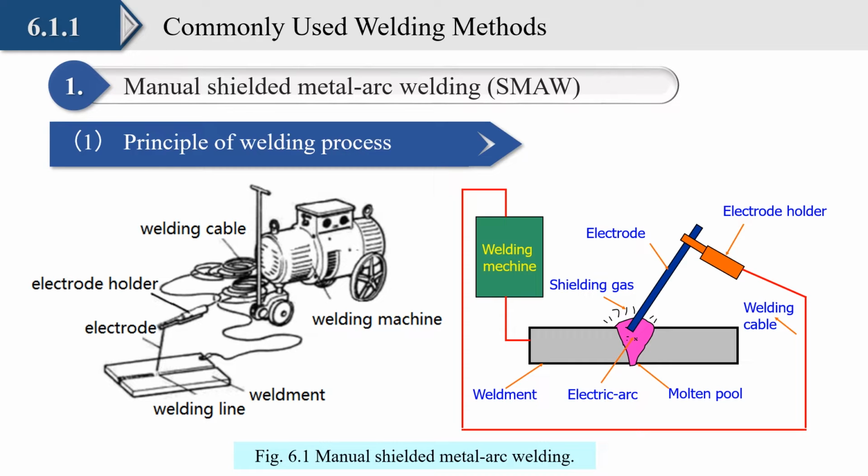During the welding process, an electric arc is formed between the end of a coated metal electrode and the steel components. As the electrode coating decomposes, it forms a gas shield to prevent absorption of impurities from the atmosphere.